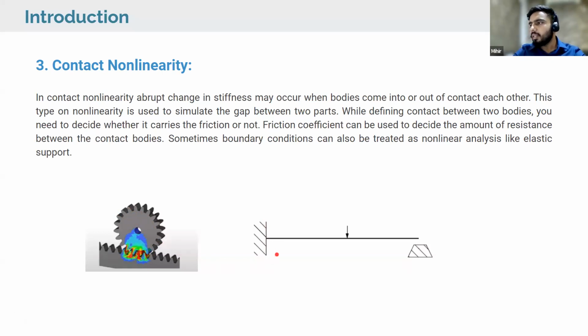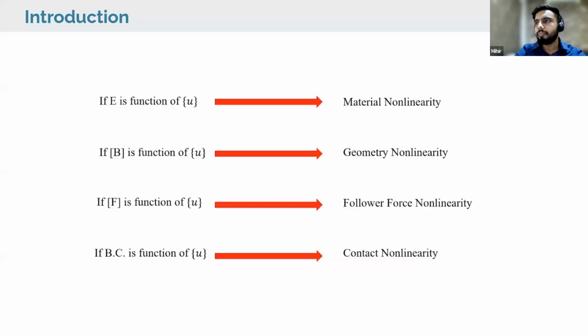Even if we talk about a civil example, I have a cantilever beam where I have some prop support at this end, but there is some gap between them. When a small deflection is taking place, it will act as a proper cantilever. But when it gets the support from here, it will be a propped cantilever, with the forces distributed among the supports. In this way, the stiffness of the structure will also change afterwards. This is based on the contact nonlinearity.